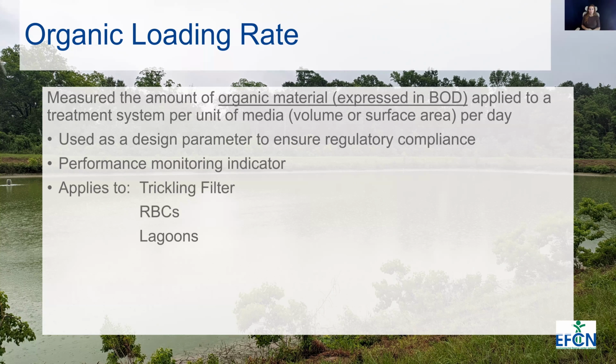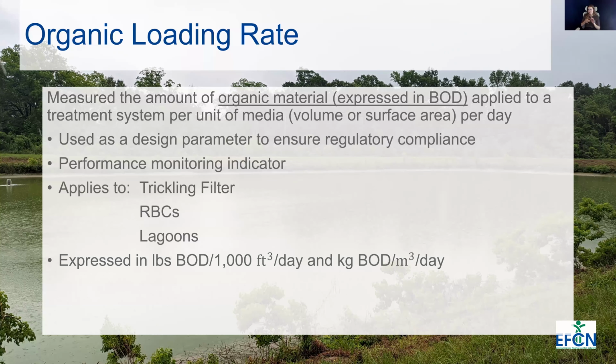This typically applies to things like trickling filters, RBCs, and lagoons, like we mentioned. And it will usually be expressed in pounds per day per 1,000 cubic feet of volume, or it can also be 1,000 square feet as well. So it seems like an odd unit. I'll show you guys how to use that though.